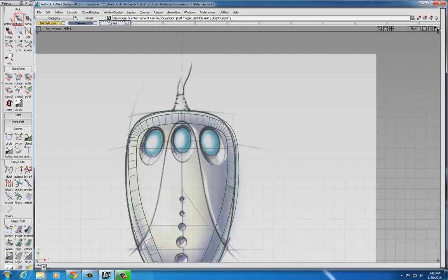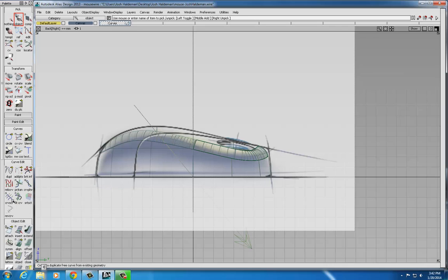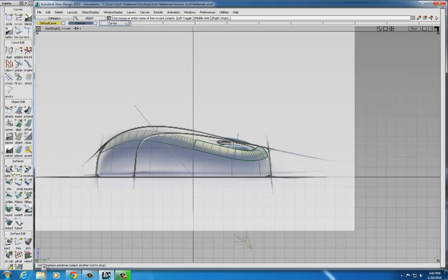rest. So in order to create them, the first step, like I said, is go to the right view. I'm going to go down to the Surfaces menu, and I'm going to choose the Primitive Sphere tool. That's the first tool there in the upper left-hand corner of the Surfaces menu. To place this, I don't need to click in or snap to any surface here. I'm just going to place it right about where that vertical line is and the top surface of the mouse, where those 2 lines intersect. I'm not going to get it exact. I'm just going to place it approximately there.